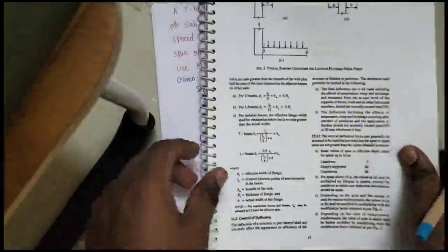If you come to page number 39 in IS 456, they have given a chart, that is the reduction factor for ratios of span to effective depth for flanged beam. So we need to consider this reduction factor while solving the L by D ratio. Here they are finding this reduction factor based on the ratio of web width to flange width. So first we need to know the web width of the beam. So we are going to assume the web width and we are going to calculate the value.